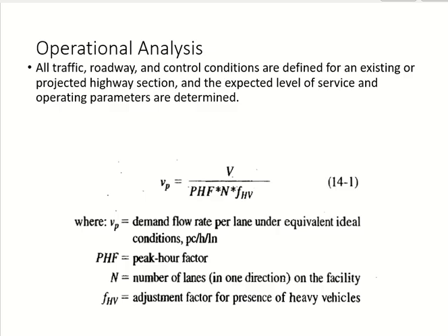If you have 5,000 together, it will be completely different. The traffic will be completely different. You are mixing 2 directions together, so you will be getting different answers. The numbers could be correct, but you will get different answers. So we take level of service for each direction separately for any type of highway.